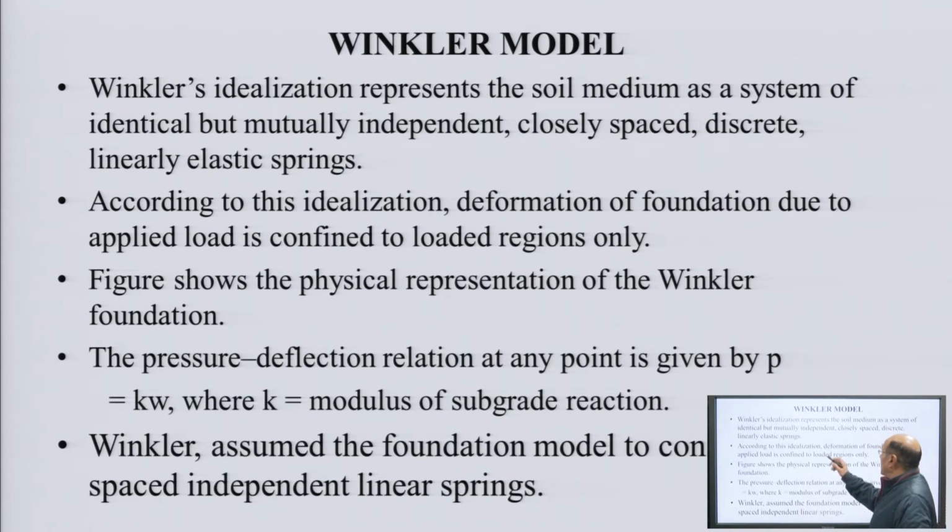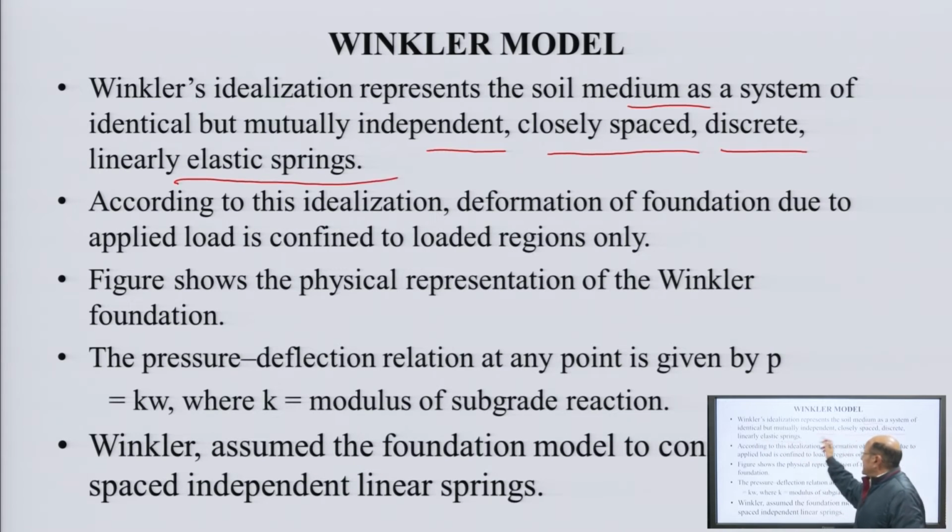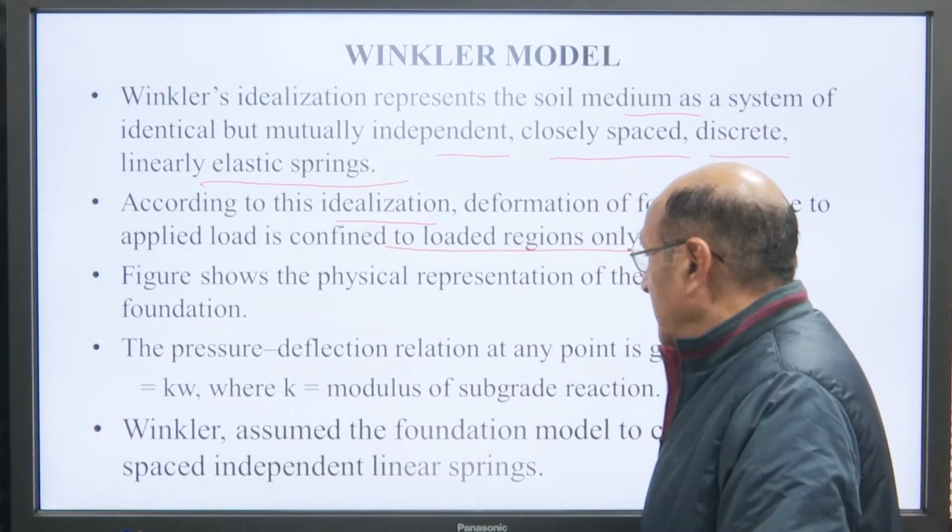Winkler's idealization represents the soil media as a system of identical or mutually independent, closely spaced, discrete, linearly elastic springs. According to this idealization, deformation of the foundation due to applied load is confined to the loaded region only.